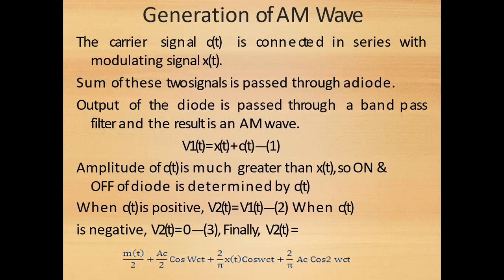The switch will be in closed position, so that the input message signal will be applied at the output when the carrier signal amplitude is higher, meaning positive.